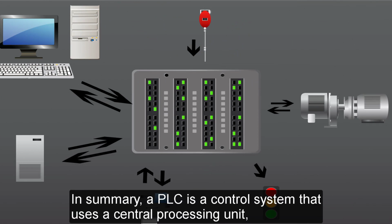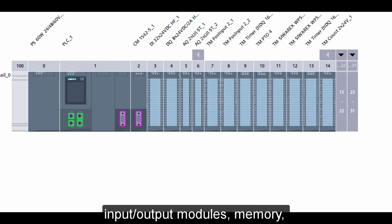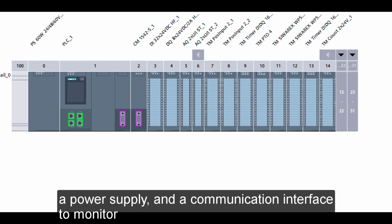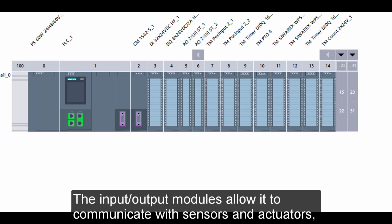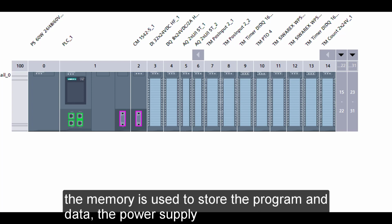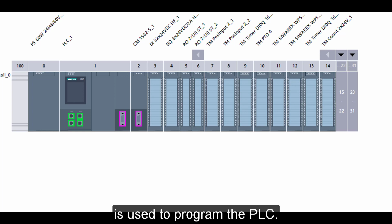In summary, a PLC is a control system that uses a central processing unit, input/output modules, memory, a power supply, and a communication interface to monitor and control equipment and processes. The input/output modules allow it to communicate with sensors and actuators. The memory is used to store the program and data. The power supply provides the necessary power to run the system, and the programming device is used to program the PLC.